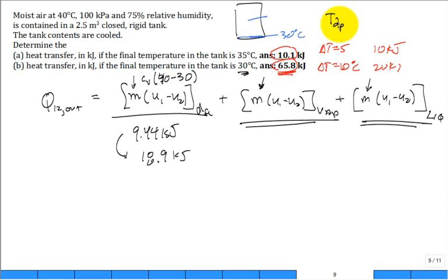It's calculatable. I have a bunch of calculations here, but I don't have the piece of paper that gives me the numbers. But that's how you do that. So at the end, this is saturated air at 30 degrees C. I can now calculate how much is the water vapor in saturated air at 30 degrees C. That's what stays in the vapor. It started in the vapor, stays in the vapor. What liquefies then will be the mass that started in the vapor at state 1 minus the mass in the vapor at state 2 that I just calculated. So I find out how much turns into liquid.